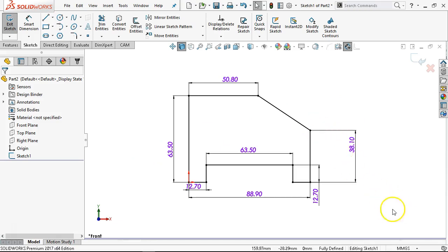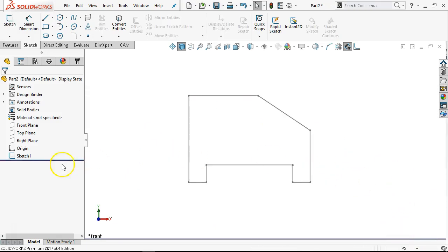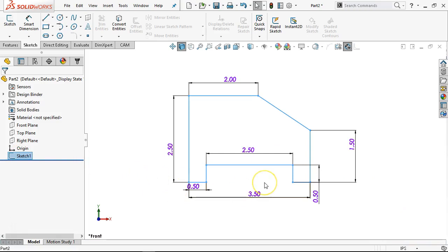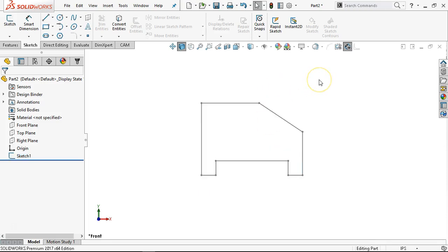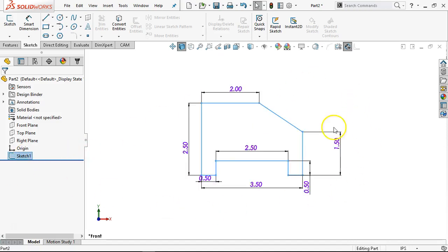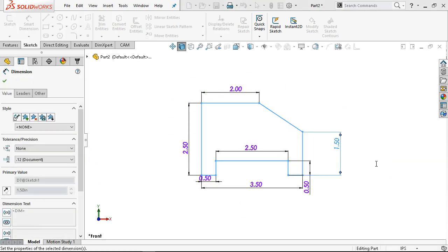And then we're in the millimeters, grams, and seconds. All of my dimensions updated. I'm going to switch back over to inch, pounds, and seconds. It kicks me out again. And then I can double click if I want to just see the dimensions. One of the reasons why you don't need to put dimensions on the solid is because that double click pulls them into view, and then as soon as I click out, they're gone again. So it's a quick, easy way of showing I can verify, this needed to be 2 inches for whatever reason.